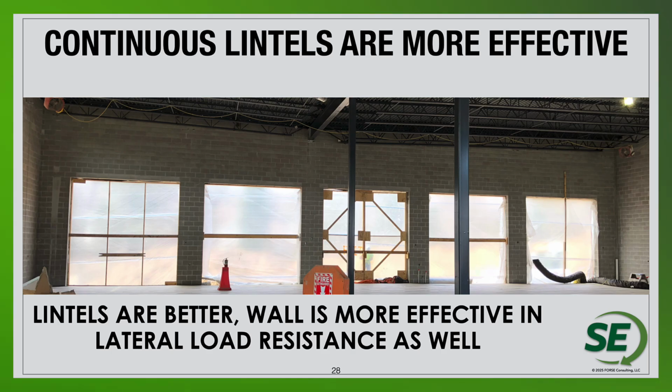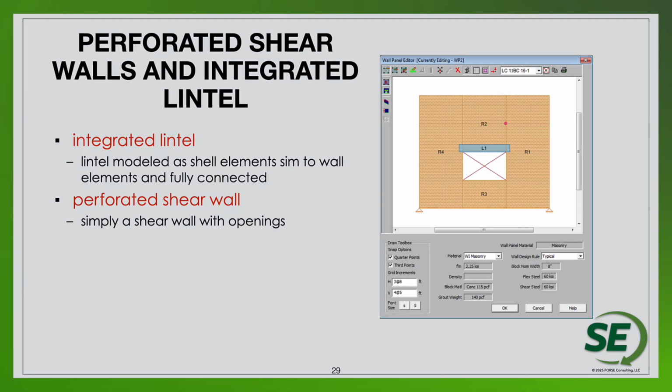And here you can see one of the elements as constructed. So again, making sure that we have a good understanding then for when we have a continuous lintel, what type of analysis is going to be required for that element, is where we start to look at finite element analysis as a very good tool for understanding the overall forces in those masonry lintels. And so certainly that's going to be the type of element that we need to be a perforated shear wall. So certainly looking at the forces in a lintel relative to the forces in the shear wall, how the flow of forces moves through that element, all going to be very important.